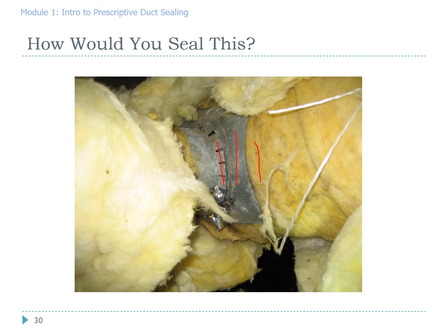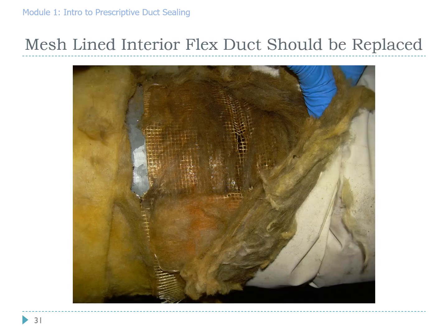If it was, we would not use it for furnace filters. We would have to remove that, seal and screw down the takeoff, with mastic between the takeoff and the sheet metal underneath it. In addition, we would have to bend these tabs in a more cohesive fashion, put some screws to it, and seal that. If all we did was coat this with mastic and coat this with mastic, the seal would not last long, nor would it be effective.